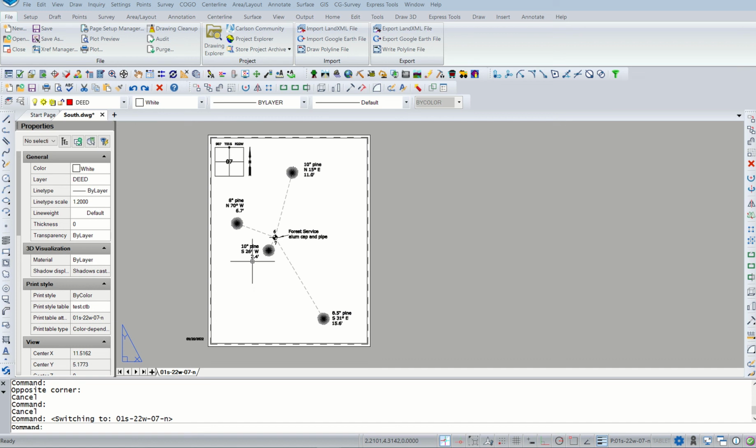In a plat boundary survey situation, if you have room, you can draw out where those references are, or if you don't have room, you can list these bearing distances and descriptions in a row or in a table to one side, or whatever's convenient.